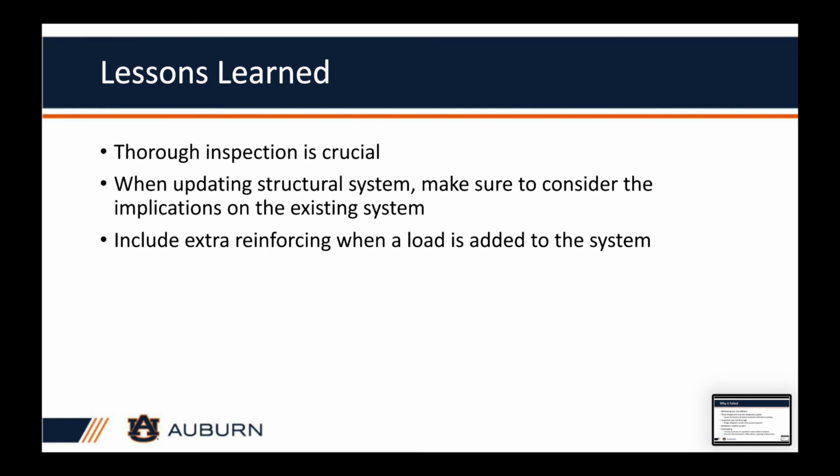The lessons our group learned: first was that thorough inspection is very crucial. Second, when updating a structural system, you need to make sure to consider the implications on the existing system. And lastly, include extra reinforcing when a load is added to the system.